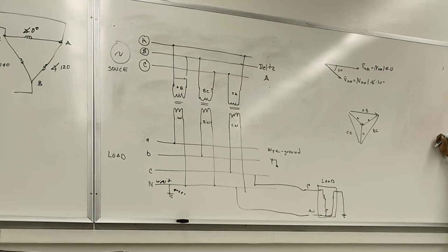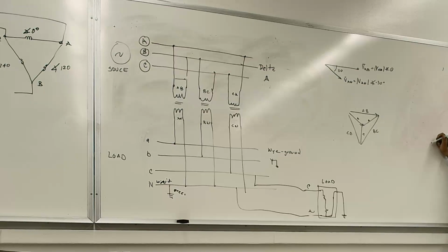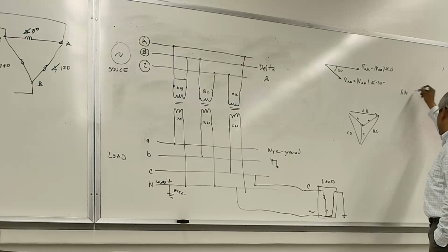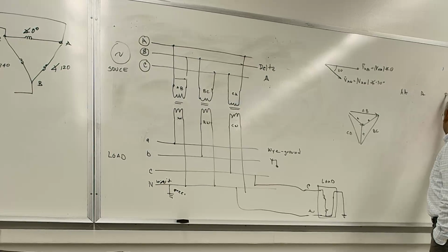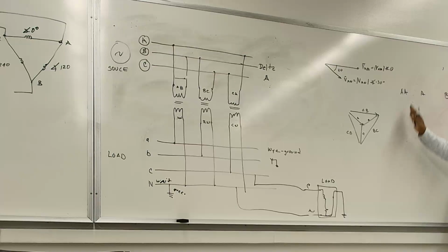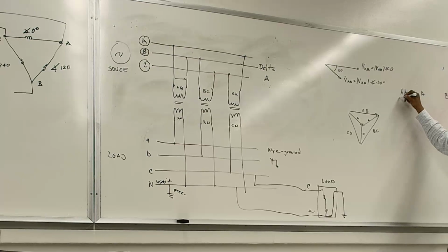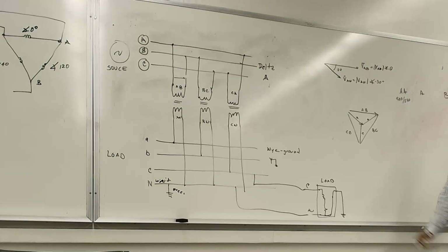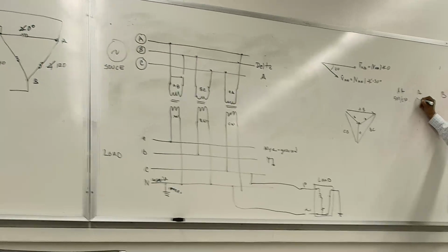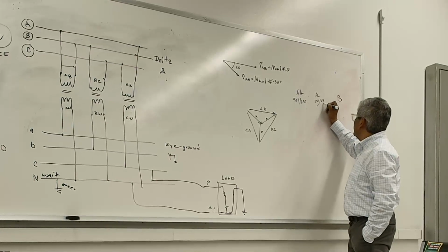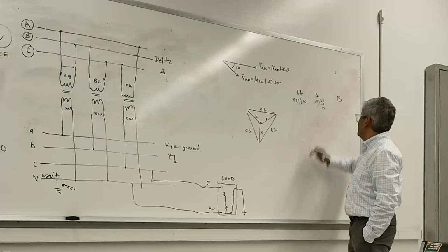I'm going to use Edison as an example. Southern California Edison has three, they call them AA systems, A systems, and B systems. The AA are substations that transform voltages from 500 to 230 kilovolts. The A are stations that transform from 230 to either 69, 66, or 115 kilovolts.